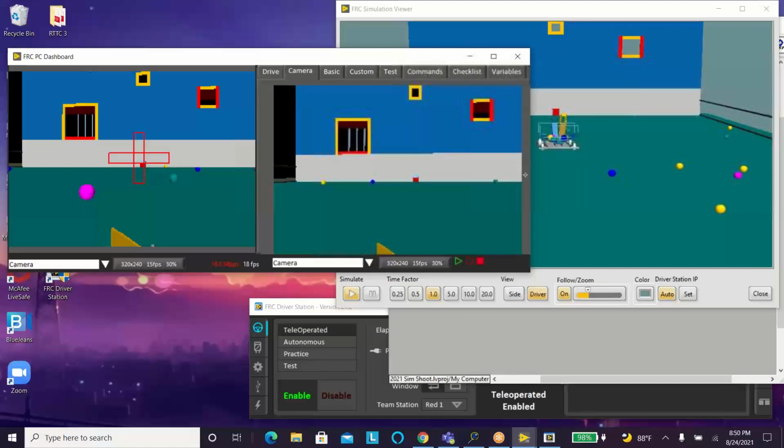The one drawback I would mention is the bandwidth of the RoboRIO is limited when it comes to image processing. So what we've done here is we haven't really taxed the camera and image processing on the robot itself. What we've done is put a crosshairs in the video stream of the dashboard, and it doesn't take that much overhead as far as bandwidth.